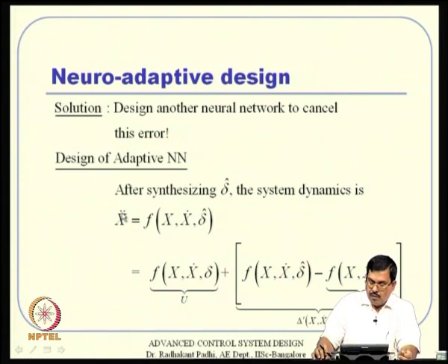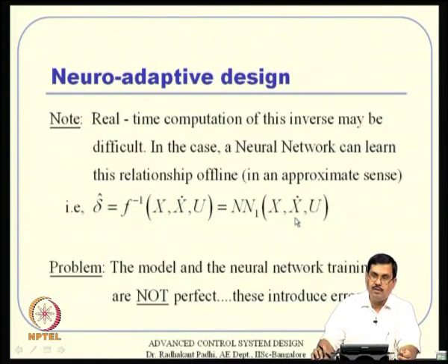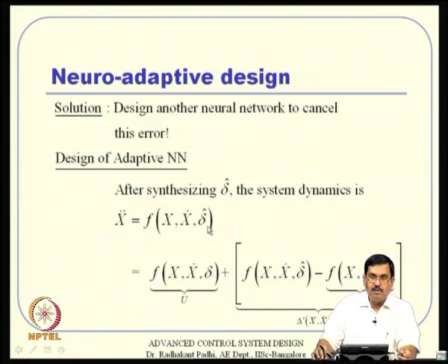Okay. Now, what is this? Let me interpret that this particular thing is nothing but my ideal pseudo control. My delta is modified in such a way. Now, delta hat is something that I am computing with this function, but delta is something else. Delta is computed in such a way that it is exactly my pseudo control. Okay, that is the whole idea there. Then what is the error? Error is nothing but this minus that. Whatever I have here, this minus that introduces some error, so that error I will call delta prime.